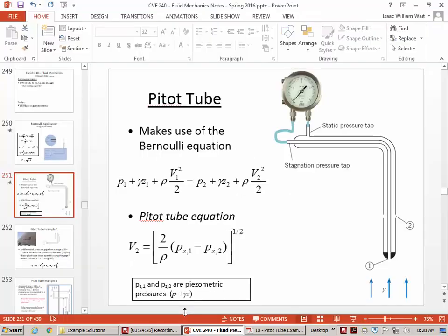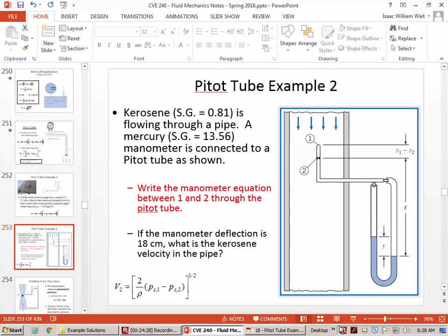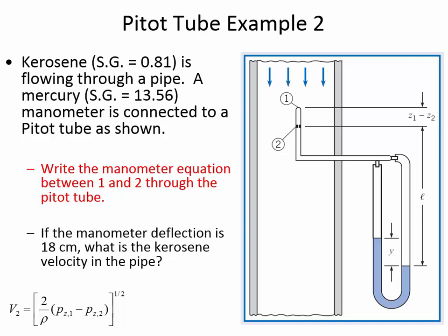All right. Well, what if we use the pitot tube in a liquid instead of using it in a gas? Just now we were working an example of measuring the velocity of air as an airplane is going through the atmosphere. We can also use it, for example, in a pipeline, because we would sometimes want to know what is the velocity of a liquid flowing through the pipeline. So in this illustration, liquid is flowing from top to bottom inside of a pipe. This pipe is vertically oriented, and it's actually kerosene that's flowing through it.